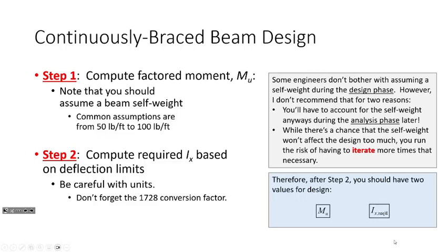If you're designing a building that has significantly high floor loads, like if you were designing a floor system for a library, I'd probably bump those up because libraries carry 150 pounds per square foot. A building like this doesn't. So you just got to be engineers about it and use your judgment.